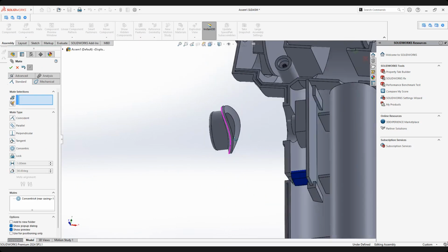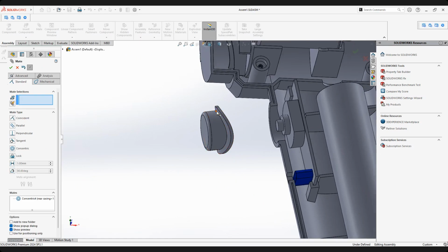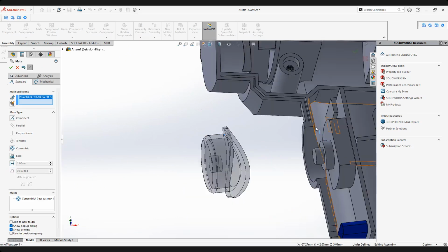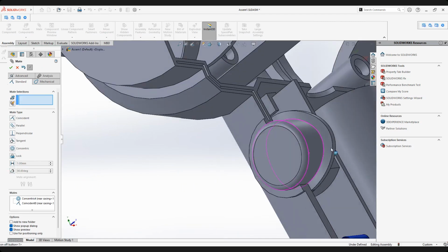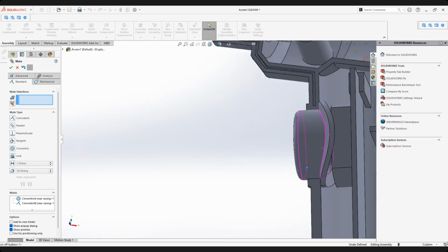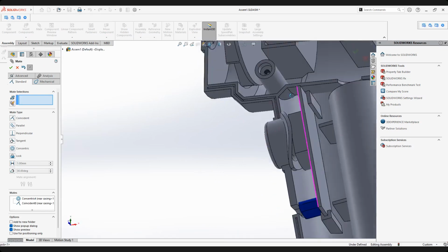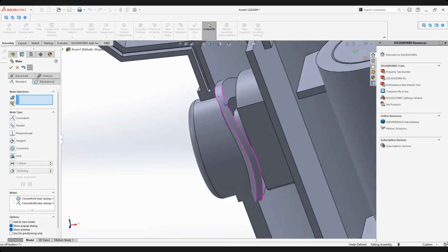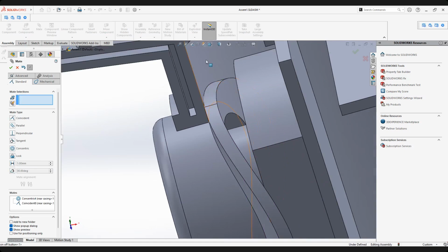I have the concentric relation, but I did mention to you guys about this point. If you look at my video, how I do it, I have a reference point there. Must mesh with this one, this corner. So it's in line. Okay, this already cannot be rotated, right? This is good, already in fixed mode because point to point. You can see it's nicely blended. Look at my video, how I create this power button, nicely meshing and blending with the shape of that internal surface, right?